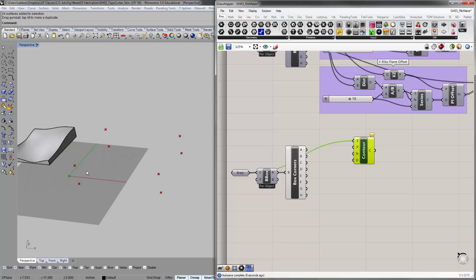So the first contour is the X direction contour, right? And so the start point for that is obviously this, which is the A point. And then normal direction. Right now, 0, 0, 1 means it's going upwards in the Z direction. We want it to go in that direction. So because this is a vector, right? It's an arrow, and you can actually see this here, that's a vector.